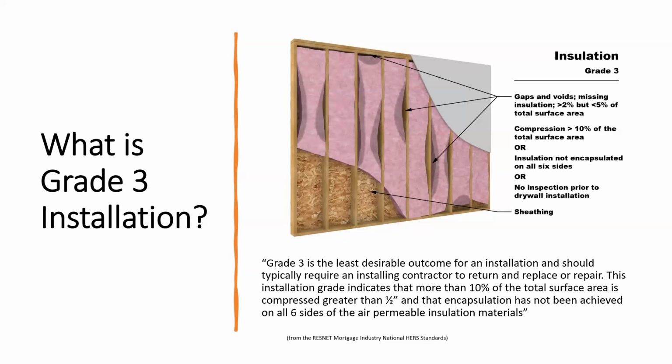It's a gap or a void of insulation. But what you have to look at is if you have a compression, once it's sheetrocked in the front, there will be a void of insulation directly behind the sheetrock. And that's what a third party or energy verifier or even a building official should look at and determine, is that correctly installed per the manufacturer's recommendations or instructions?